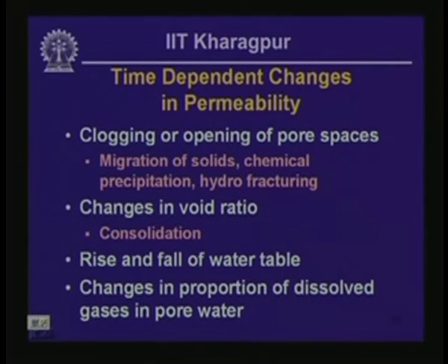Second thing is changes in void ratio. Void ratio in fact might change as time passes, and that is particularly true in case of fine grained soils. In case of fine grained soils, depending on pore water movement, the stress may increase.